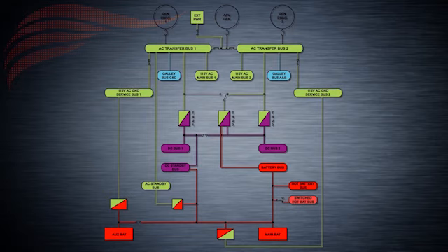Sometimes during ground operations that involve only cleanups or quick checks, all electric buses don't have to be powered by ground power. For this reason, even though ground power is capable of supplying power to both AC transfer buses, and therefore to all the systems that take power from them, for the purposes of ground servicing, a ground service switch in the forward attendant panel allows the external ground power to provide energy only to the AC ground service buses.